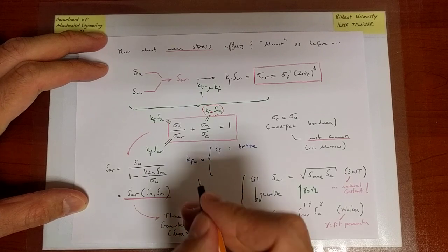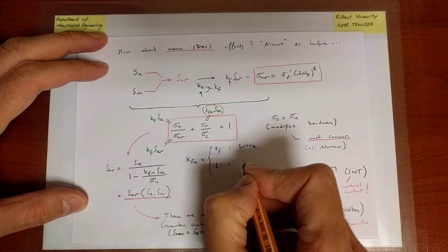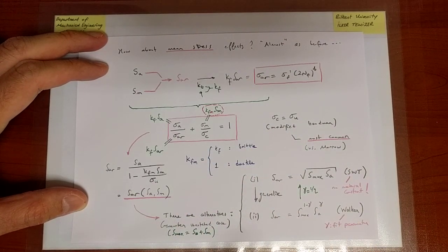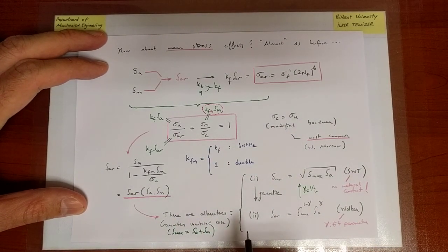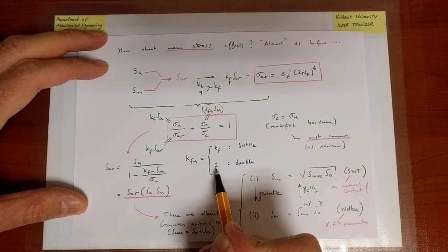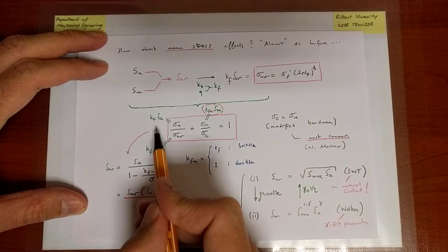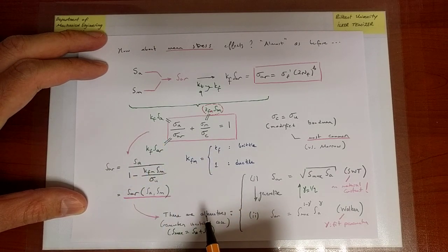if one works with brittle materials. On the other hand, when one works with ductile materials, the convention or the argument is that one can remove the influence of stress concentration altogether. In other words, take the fatigue notch factor to be 1 for the mean stress only. The value on the alternating stress remains the same.